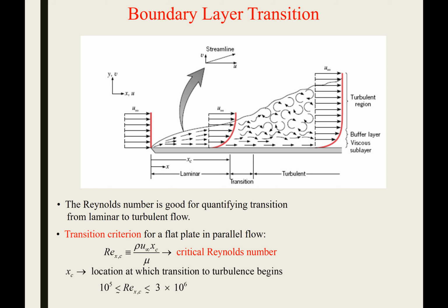So the Reynolds number is still going to be really important in this class, but there are going to be different geometries. And so mostly by empirical results, I think they found that depending on your geometry, the Reynolds number at which you transition from laminar to turbulent may be totally different.